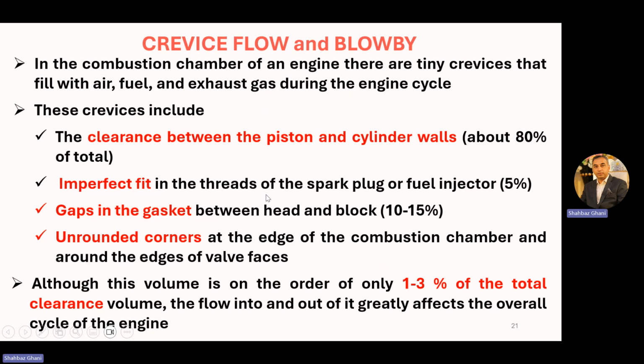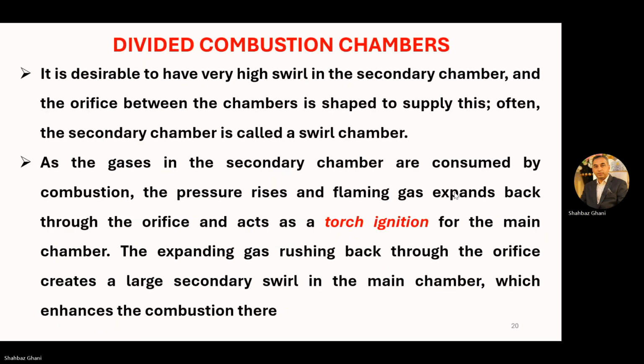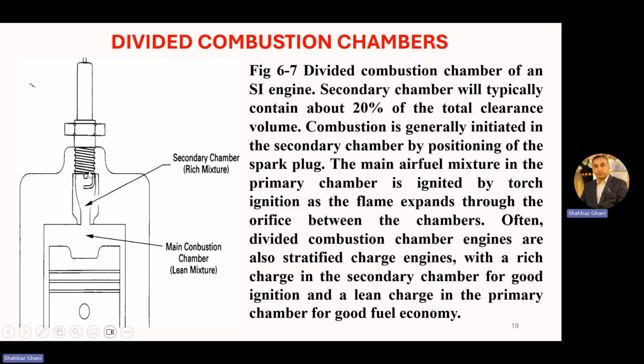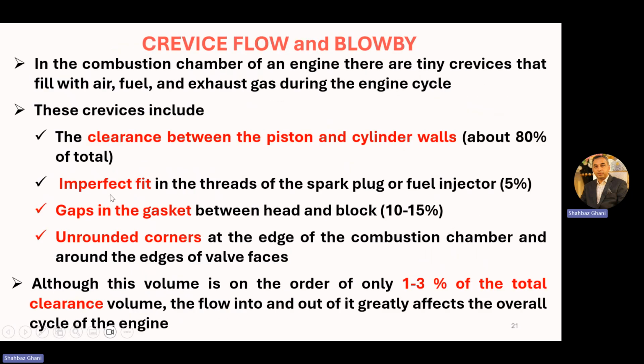Next, imperfect fit in the threads of the spark plug or fuel injectors. If we place this spark plug or fuel injector in the head, then due to the imperfect fit in the threads, we have about 5% of the crevice volume there. Gaps in the gasket between the head and the block account for 10 to 15%.